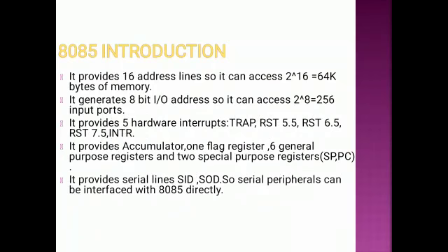8085 has 16-bit address line and 8-bit data lines. If we know the address lines of any processor, we can find out its memory capacity. Similarly, as you saw in the PPT, we have 2 raised to power 16 equal to 64K bytes of memory capacity of the 8085. We can calculate by using the formula M is equal to 2 raised to power N. We can calculate the memory capacity of any processor.